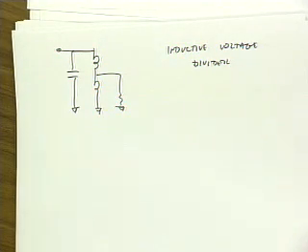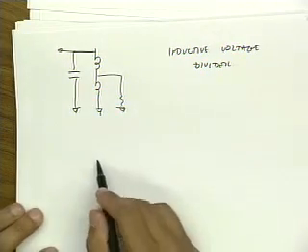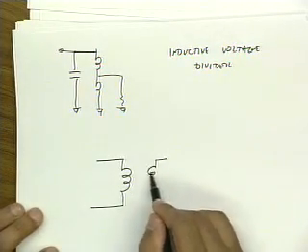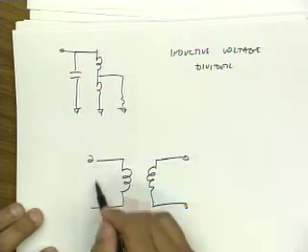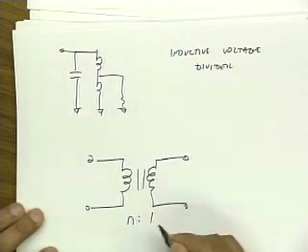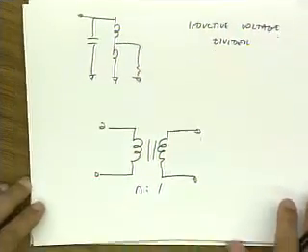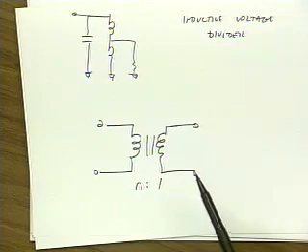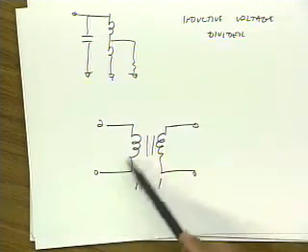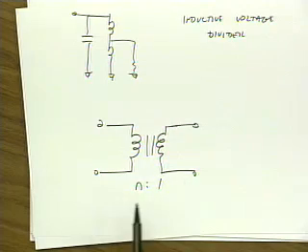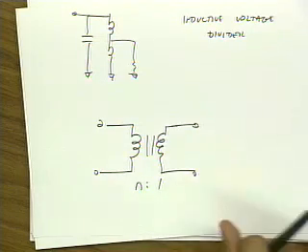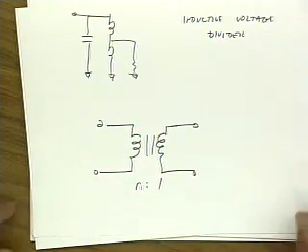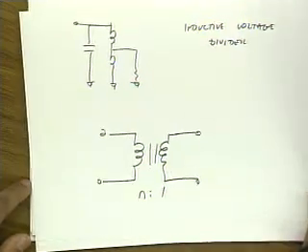Okay, and you know, let's not forget our old favorite way of doing impedance matching. We could also use transformers, right? This is an N-to-1 transformer. The very name transformer comes about because it can transform voltages and currents, and therefore transform impedances. We'll talk a lot more about real transformers later in the class, because unfortunately, anytime you build a transformer, it doesn't really look like this. It's a lot more complicated. But for now, let's just say that this is also an option for doing impedance matching. Okay? Questions or comments?